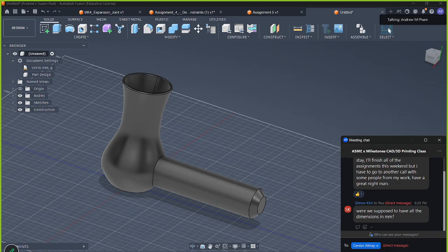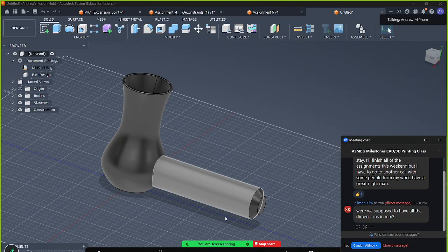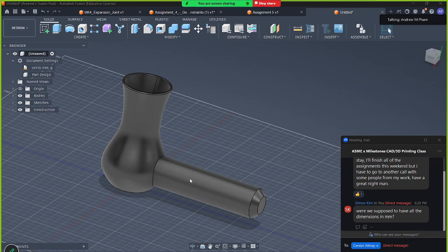So in this case, this timeline is pretty straightforward. We made a bunch of planes here, made a bunch of sketches, we created that loft, and then we shelled it out. We added that fillet, more planes, and then that extrusion and chamfer, right? But we have the ability to change the order to change the model, right? So let's say we wanted this handle to be shelled out, right? We can make sure the shell happens after the extrusion, but we can only do that if there's no dependencies.